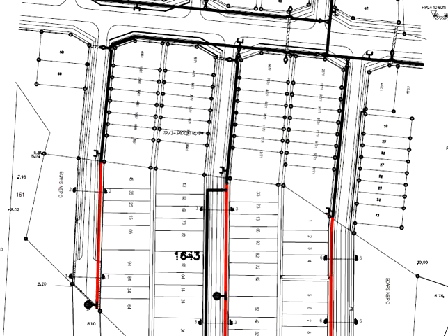Why do we need to refer to the engineering plan? Because in the engineering plan, there are culverts proposed. In the existence of a culvert, the water mains will have to go over the culvert. That leads to the mains not being at the same elevations. There may be traps of air bubbles in the pipe. The air bubbles in the pipes will disrupt the flow of the water in the pipe, and this can affect the functionality of the piping systems.